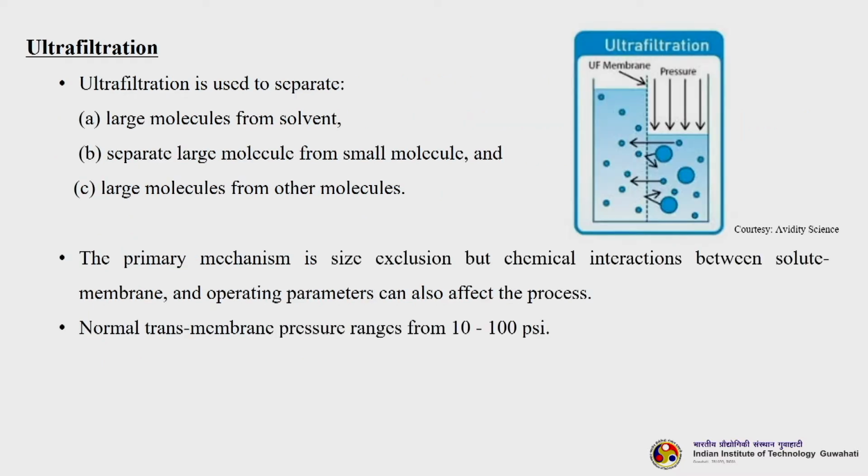Next is ultrafiltration. Ultrafiltration is used to separate large molecules from solvents. The molecule sizes are usually larger than those of microfiltration, and it separates large molecules from smaller molecules, basically fractionation. The primary mechanism is size exclusion, just like microfiltration, but chemical interactions between solute and membrane and other operating parameters can also affect the process.